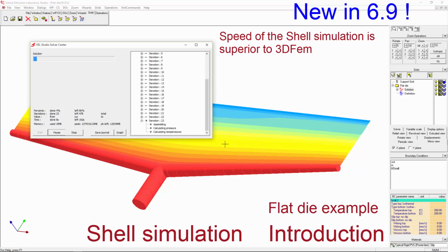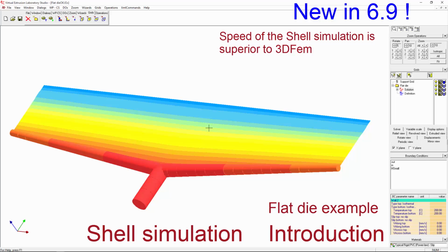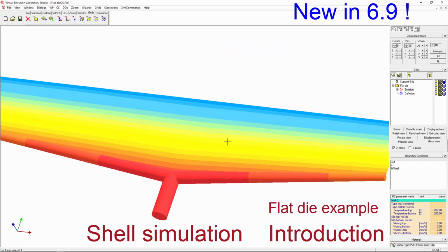And you can see the pressures and other variables being updated during the solution, updated after every 50 iterations. And the calculation is done in maybe 1 or 2 minutes maximum. We don't need too many iterations, probably something like 90, 120 iterations would be very sufficient for a good quality solution. The solution calculates not only the pressures, but also the velocities, temperatures, and other results. Okay, the solution is done, and we see the pressure contours.